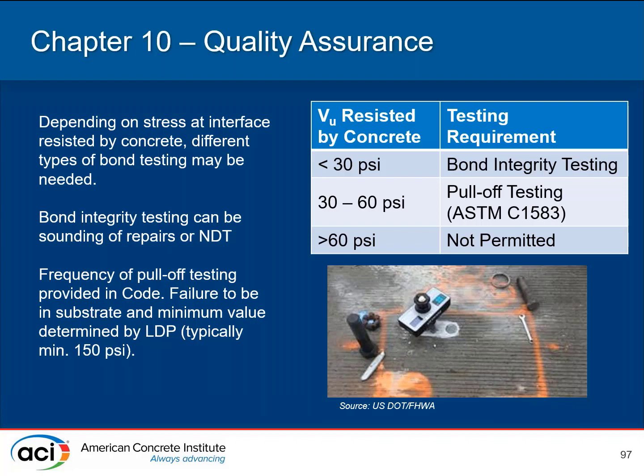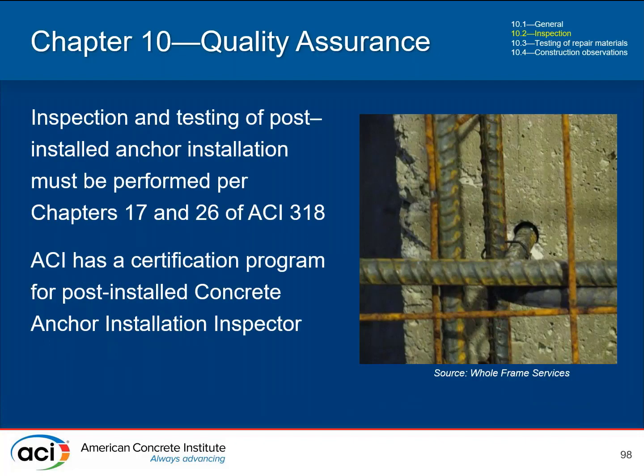So I definitely wanted to mention it. Another one that is very common in repair: it does occur in new structures, but it's much more important and much more frequent in the repair industry. That's post-install anchors, so your epoxy anchors. They're needed for a variety of reasons in repairs. Often you're just running out of space and you need to develop and anchor your bars, one very common case.